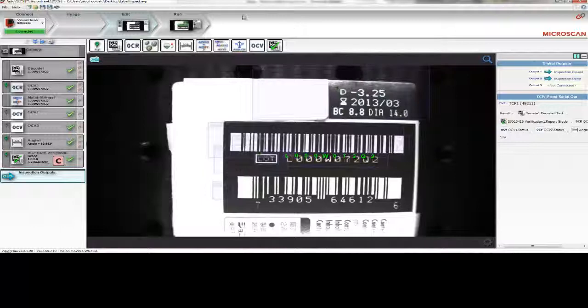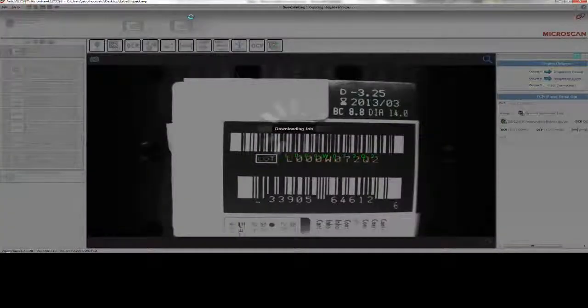After completing a program, you can go into run mode. The program is then copied into the camera and saved in the flash memory. And the camera can run with AutoVision and work like a barcode reader where it's taking images, qualifies them, and based on the output, the product can be approved or rejected. AutoVision does not need to be running to achieve that.